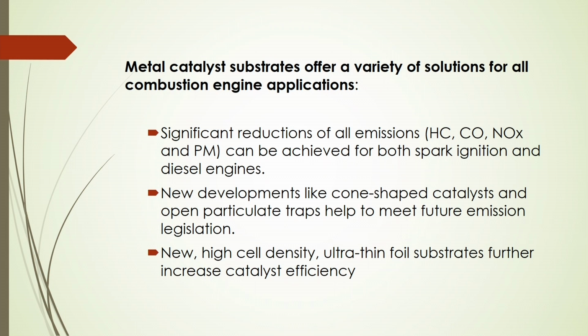And metal catalyst substrates offer a variety of solutions for all combustion engine applications. In this case, you will see significant reductions of emissions like hydrocarbon, carbon monoxide, NOx and even particulate materials, and these reductions can be achieved for both spark ignition and diesel engines.